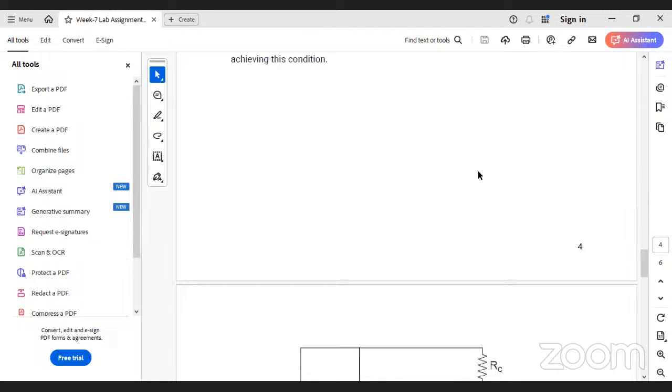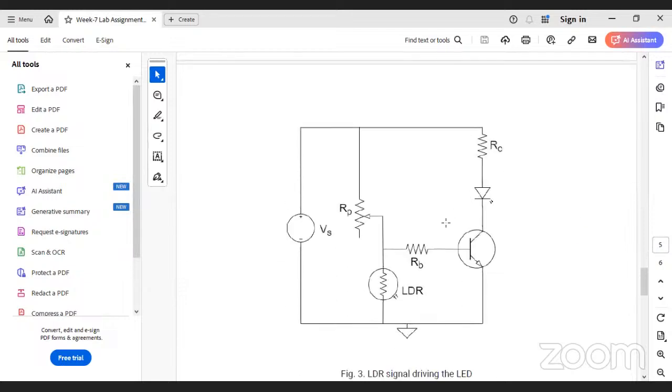Anyone has any doubt? When we are using DC voltage from the ADALM kit, channel A or B, and measuring the voltage across a resistance with a multimeter, the voltage fluctuates. I think in the previous experiment I said some repeated sweep thing is there. No, I'm saying when I measure the voltage with a multimeter.